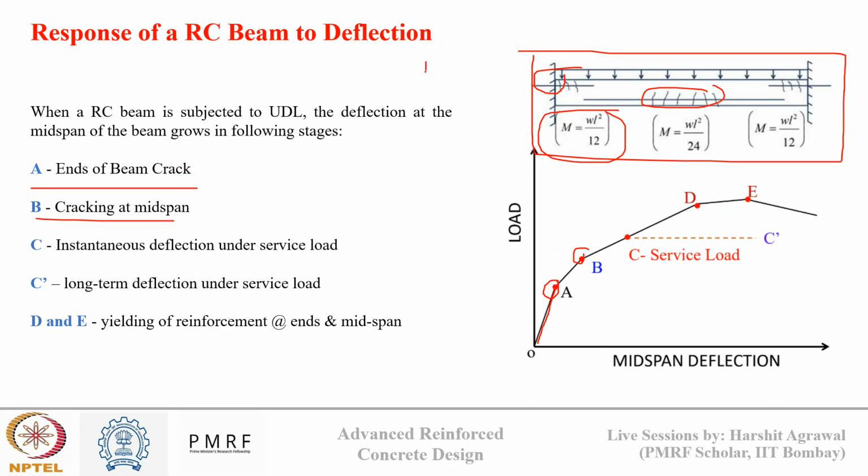So in an under reinforced section, my steel has reached the yielding. So as I'm increasing the stress, the strain in steel is increasing. So curvature will slowly increase in the steel also. So that's why the midspan deflection may increase further. Now if we keep this service load constant, then the deflection will further grow at this load also. Why? Because of creep effect.